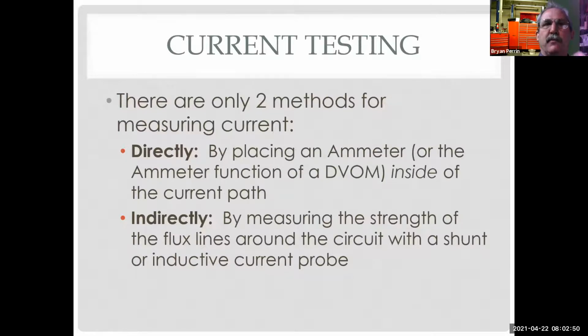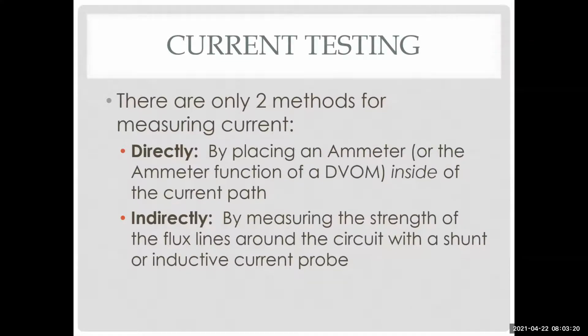So obviously, if a circuit flows too much current, it has low resistance. That can be a sign that I have a fault. On the other hand, if I have something that's not working or has high resistance, I'm going to flow less current. So I can use current to infer resistance of a circuit. I can use current to compare the same circuit under different events. Or I can use current to compare the resistance of different parallel circuits that all share a main power wire.